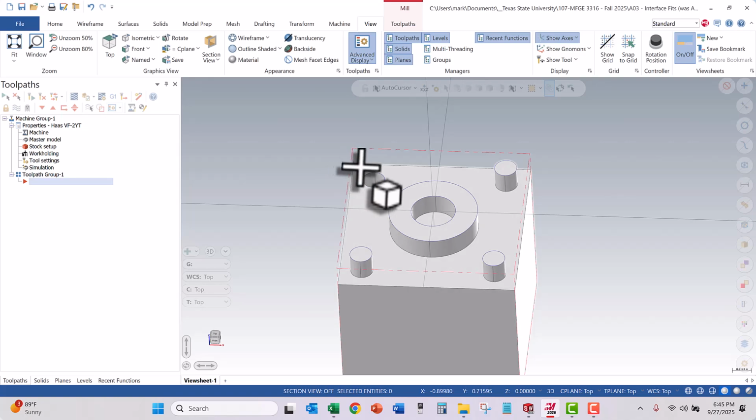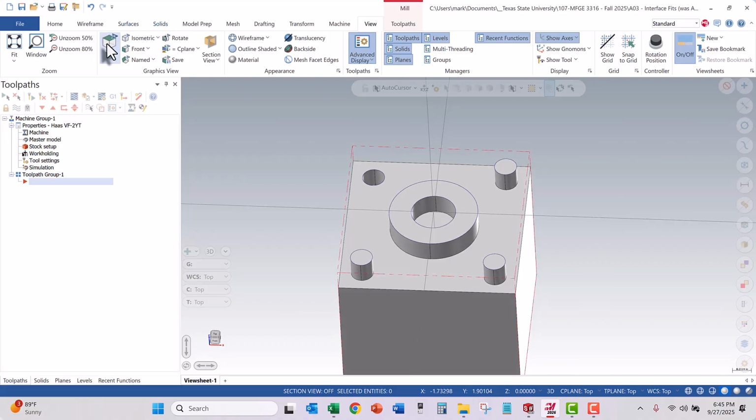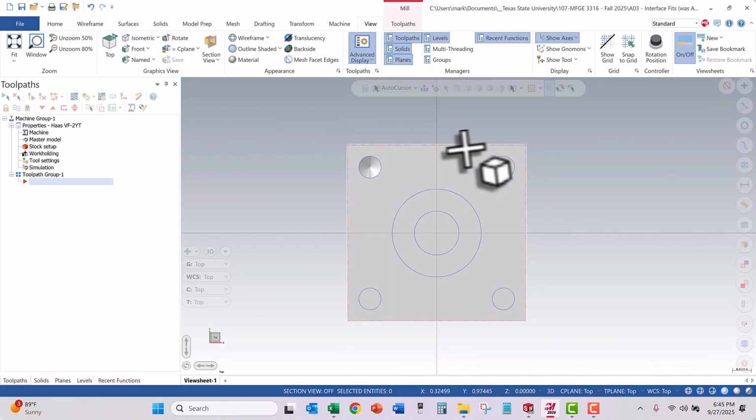So I don't want my end mill to be defined by staying inside this 2 by 2 inch square. It needs to go past that so that it can create a flat surface all the way across this top surface. So what I'm going to do is make some 2D geometry. So I want to come to top view. What I want to do is offset these edges 1/4 inch so my end mill makes sure to get out here far enough to remove that material I'm looking for.